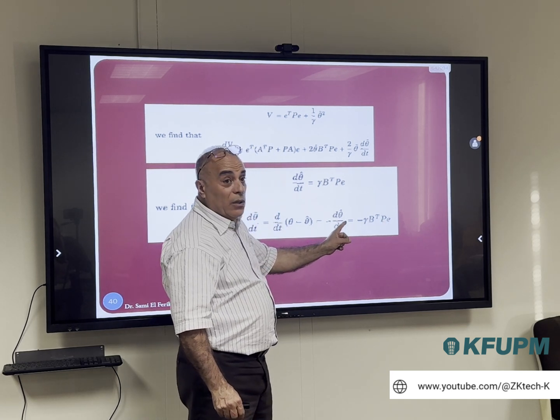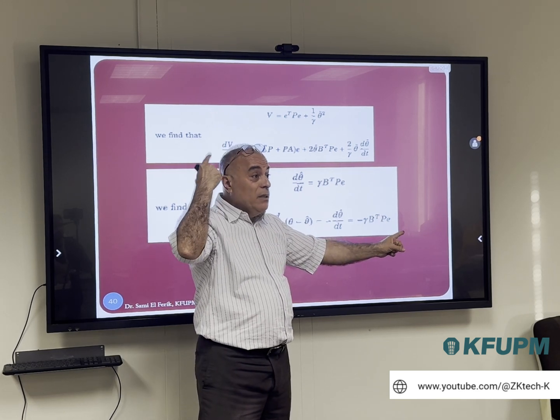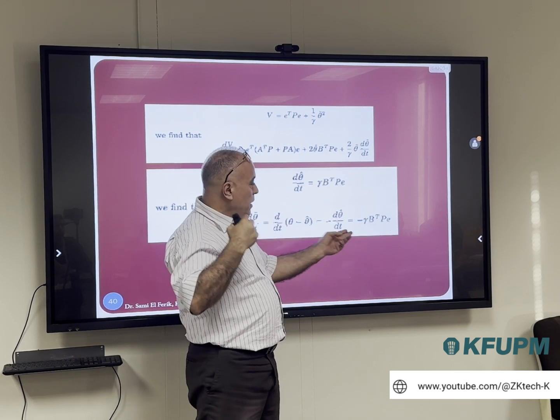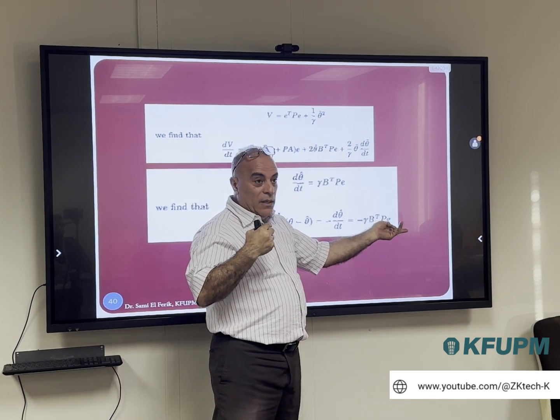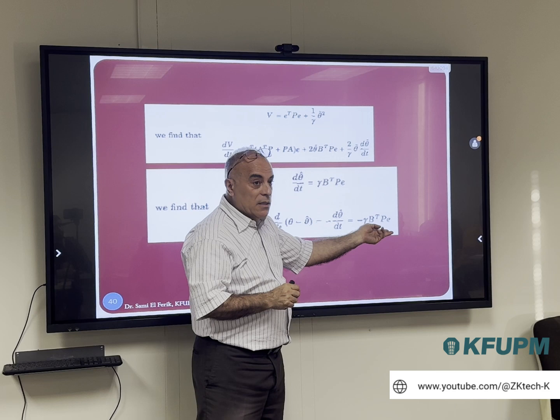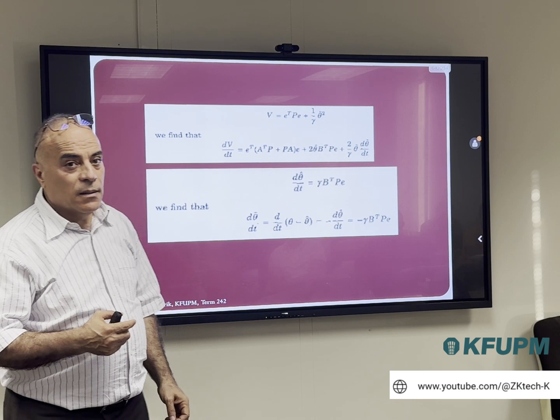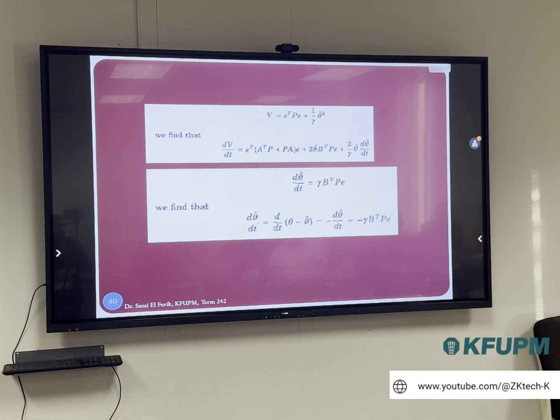This theta tilde can go to 0 if the error is equal to 0, without convergence to the real value of theta 2. The same problem that we had before. So this term can converge to a value, especially if there are some singularities and we are not close to the equilibrium. It can converge to a value, but it's not the right value. But it guarantees stability. Does it make sense, what I did with you today? Yes? Alright, I think I lost you somewhere. Anything not clear? Clear.